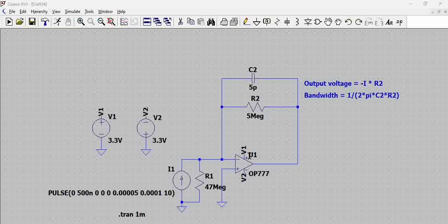Okay, that is why we see plus 3.3 and minus 3.3. And ensure that you have the bias current of this particular op amp, which can detect low currents. And also the resolution is a primary criterion. So you have to select this particular resistor such that the current here will actually be above the input offset voltage of this particular op amp.